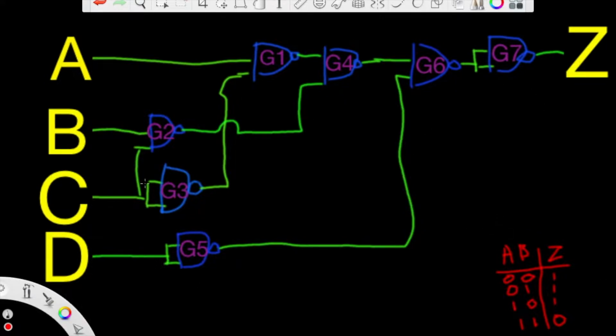And if you don't know how a NAND gate works, this is a truth table. You got 2 inputs A and B, which aren't related to these circuit inputs, it's just what the input names are, and then you got an output Z, which isn't related to this either. So in every situation except one, the output's going to be 1. The only situation where it's 0 is when both inputs are 1. So that's how it works.